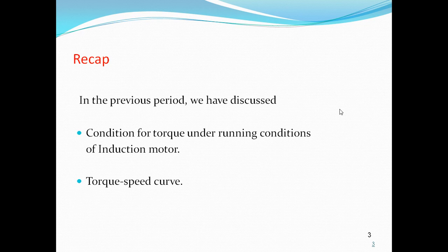The torque is maximum when the rotor resistance is equal to the reactance under running condition, that is R2 is equal to sX2. So s is equal to R2 by X2. If we substitute this in the torque equation, then we can get the maximum torque value.